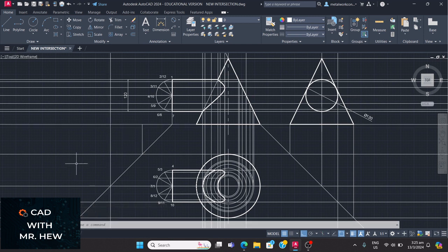So that is how I'm using a line command for that, but you could use the X line, right? So we go there, coming up there, enter. When I do it like this, I can see clearly that this is a triangle that I need. But if you use the construction line, it's not a problem. So go here, there, there, enter, right?